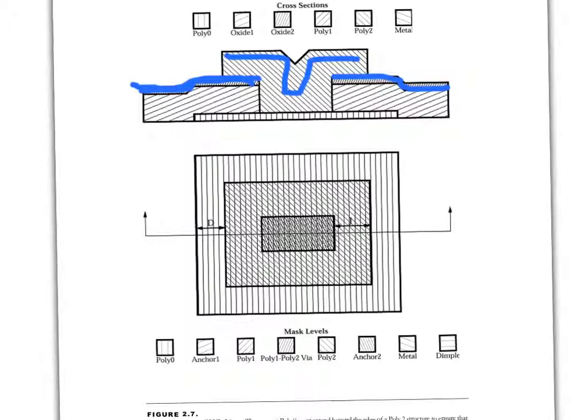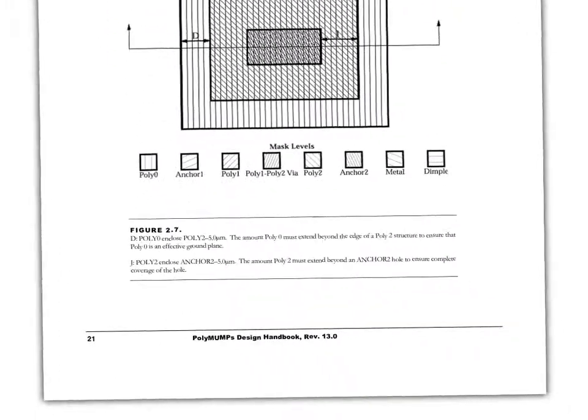It's harder to align. As you add more and more layers, like when I was at TI, we had 27 layers on some products. Well, when you're at layer 25 and you're trying to align to layer 4, it's really hard to do because you've got all this stuff in between and all this topology. So the alignment tolerances usually get bigger and bigger as you get further along the line because you can't align as well. You've got all this other slop in there from the previous layers in between. So that's why that tolerance is bigger.